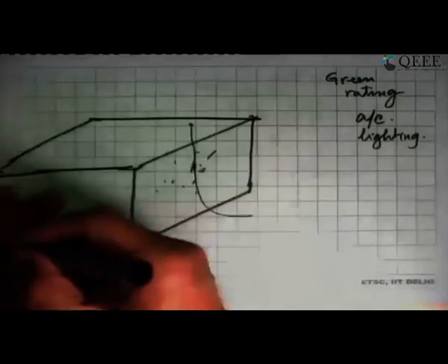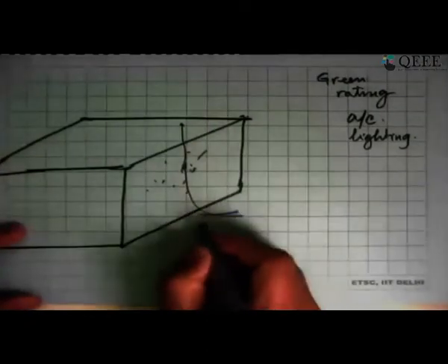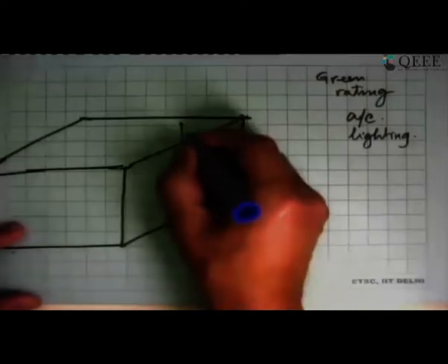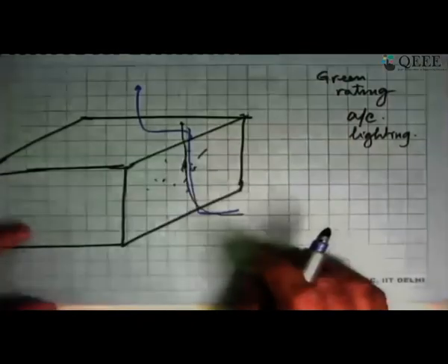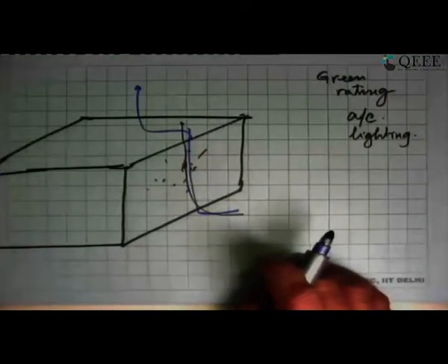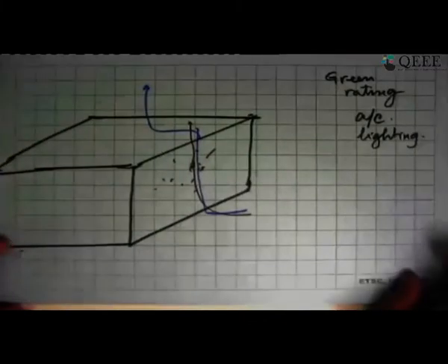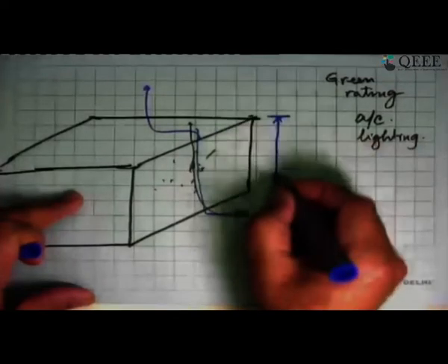Or maybe it's not even going to be like that. The ground is there, so the air will come here, but the velocity is very small. It will go up, it will keep getting accelerated, then it will bend up over this flat plate and then go up. The streamlines like this are induced by buoyancy. The correct length parameter for evaluating the Grashof number in this problem is this length.